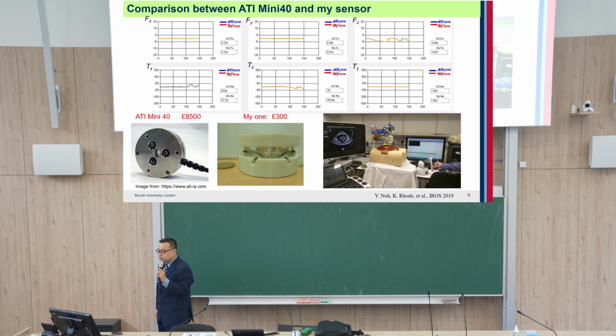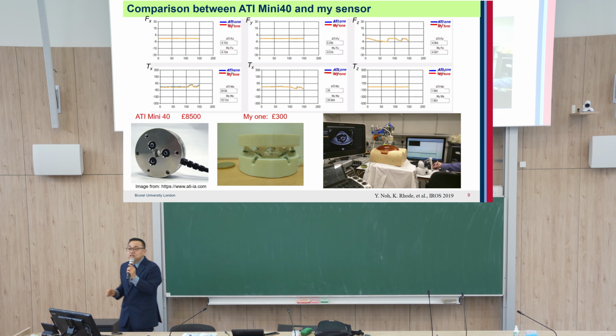And then I also have to solve some temperature issues. This sensor is slightly sensitive to the ambient temperature. For that reason, I'm designing how to compensate for this temperature. But for most sensing units, we have to compensate for temperature anyway. There's no 100% sensor which is really immune to temperature, so this is just common. Any other question?